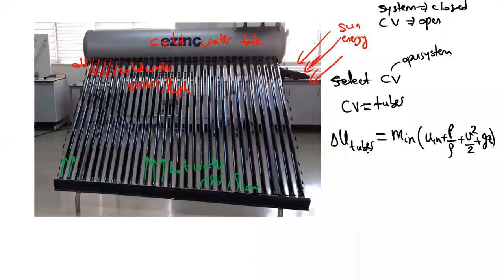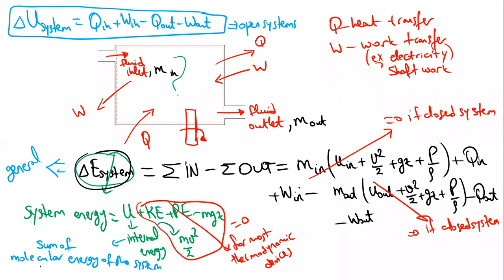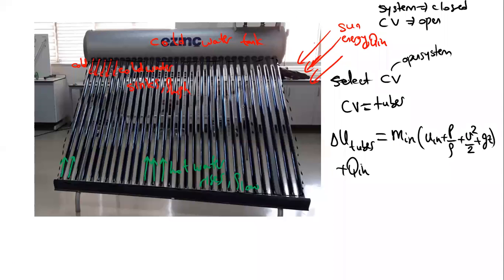Then from this open system, you will have the Q in, because the sun energy is the Q in. And then I will have the work in term, which will be 0. There is no work into the system. You can see there is no rotating shaft and no electricity. Therefore, this system will have no work transfer, and the work transfer part will be equal to 0.